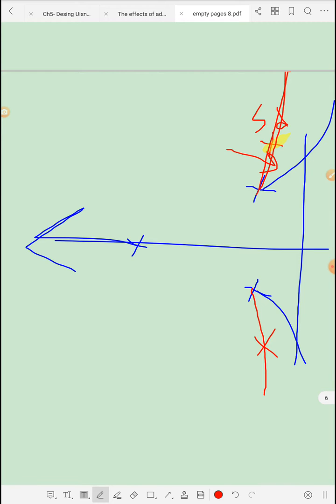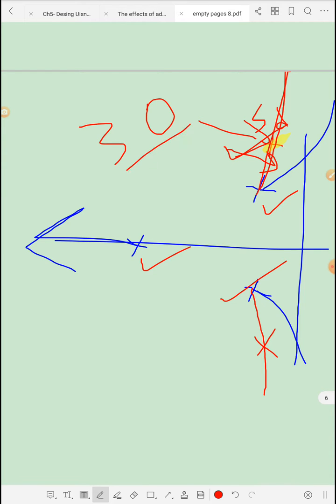and this compensator will provide the system with the deficiency in angle, because at SD the angles of the poles and zeros of the original system are not odd multiples of 180, so there is a difference. Assume that the angle at SD is 150, so there is a difference of 30 degrees. Those 30 degrees will be provided by the compensator or the controller.